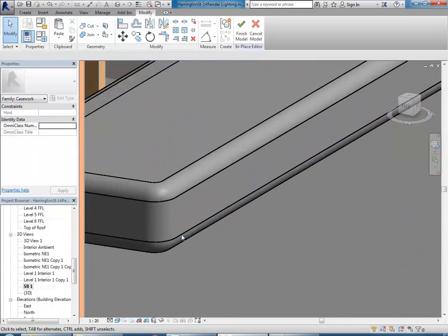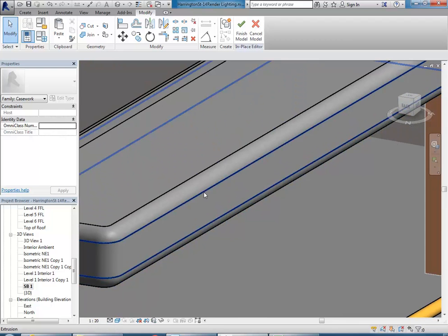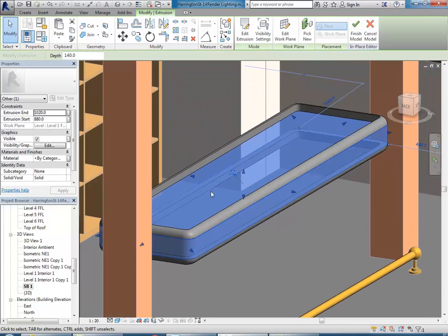So yeah, it's a bit of a process, and this is one thing I've got to say: AutoCAD has solid modelling tools, a bit like Revit. You can do extrusions and things like that, but you've had this option since the beginning to fillet a solid in AutoCAD that you just don't have in Revit. And that would let me do this in a few clicks. I could just round off all the corners with the fillet tool.